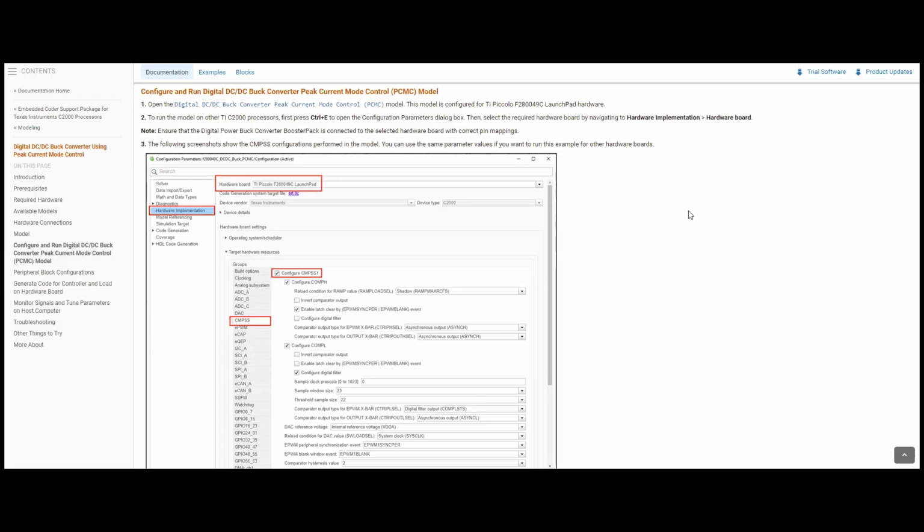Comparator high of the CMPSS1 is used for cycle-by-cycle trip of the EPWM module as part of the peak current mode control. Comparator low of the CMPSS1 is used to implement a redundant overcurrent protection scheme, and this output is configured for one-shot trip in the EPWM module. One needs to clear this trip flag to enable the peak current operation in an overcurrent condition.